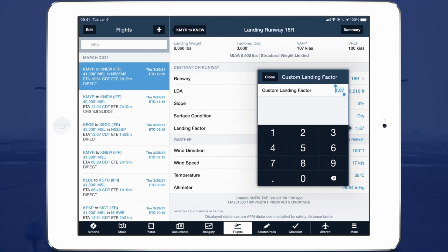For those of you who are not familiar with runway condition codes, it's part of the RCAM matrix. It is based off of the FICON code that's provided, I think since 2016 or 17. And as of November this year, it's going to be required globally because the ICAO is introducing the Global Reporting Format, GRF. And really, you're going to see FICONs everywhere being used.